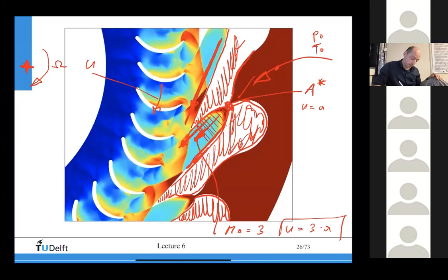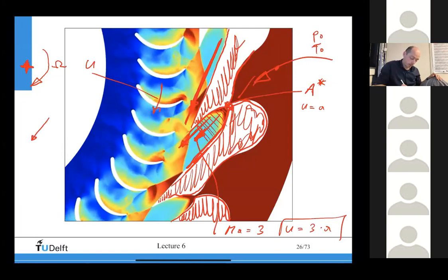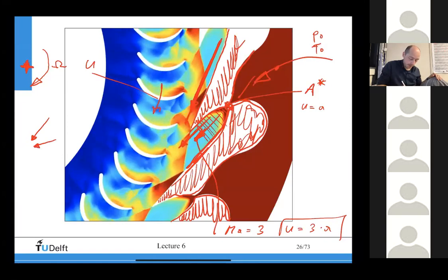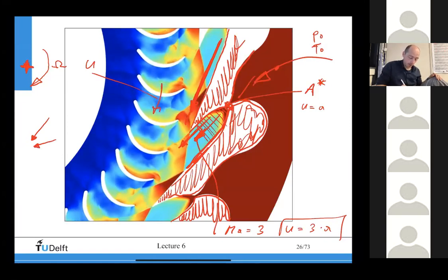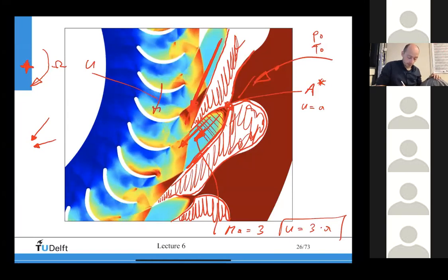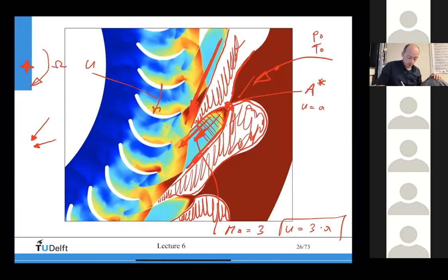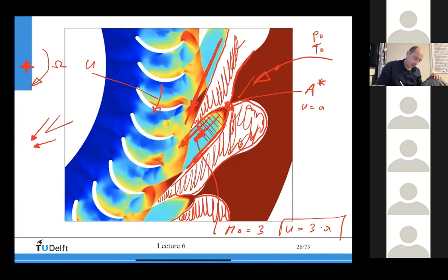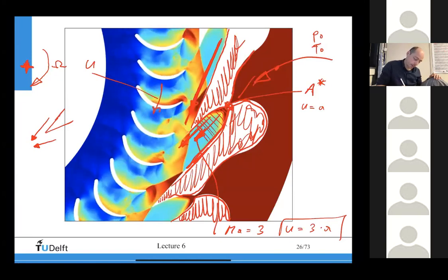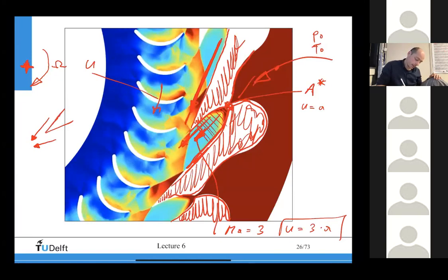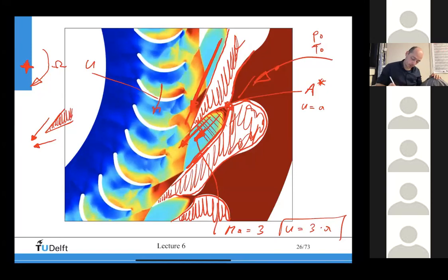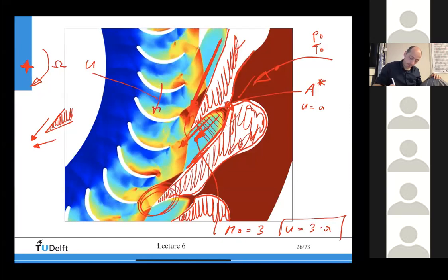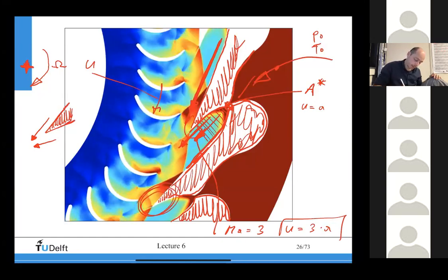So now you have two flow regions that meet each other like that, right? So at some point, they cannot cross each other because you have mass conservation. At some point, once these two flows on, let's say, this side of the stator, there's no suction side or pressure side, but on this side of the stator, this is the stator trailing edge. This guy is the stator trailing edge. It's the last part, right?